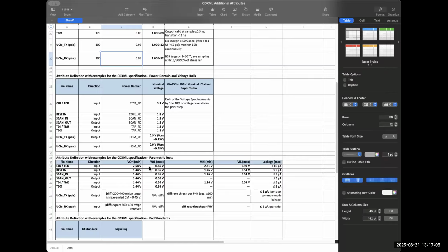And the last one is a parametric test. So today, in parametric tests, all the pads are characterized, at least for the first evaluation device. This may not be applicable for the production patterns, but the initial wafers or the initial device bring up will go through this parametric test to check the input and output low and high voltages, to check the parametric characteristics of this particular pad, to make sure that the iterations are proper and it is meeting the spec across the different